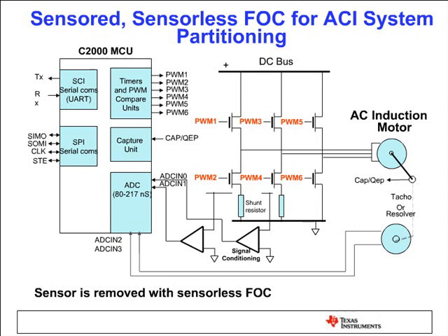But on the other hand, for PMSM type of motors, people go above 1000 PPR, pulse per revolution. And typically I use 2000 pulse per revolution for precise control. And currents are sensed through the shunt resistors in our applications.